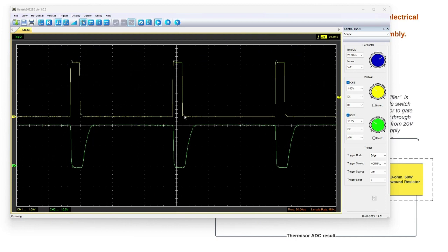So this is our PWM, pulse width modulated signal, in yellow. In green is our high voltage power supply, as seen at the low side of the resistor, the voltage on the low side of the resistor. So it's reversed. If you want to think about it, if you inverted this, when we open the switch between the resistor and ground, the voltage on the low side of the resistor rises up to, we're 10 volts per division, nominally 20 volts. So we're 20 volts on the input side of the resistor on the high side, and we're 20 volts on the low. We're not putting any current through.